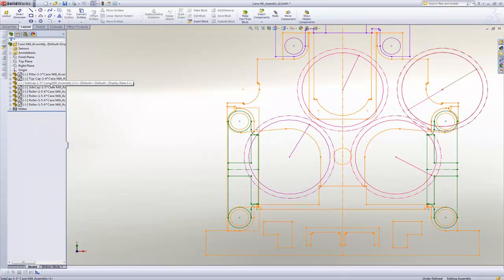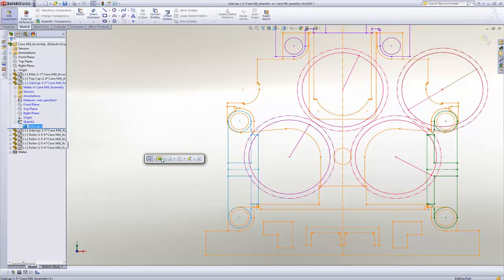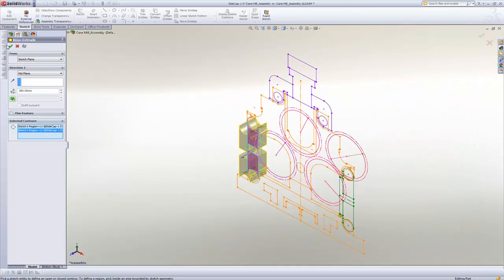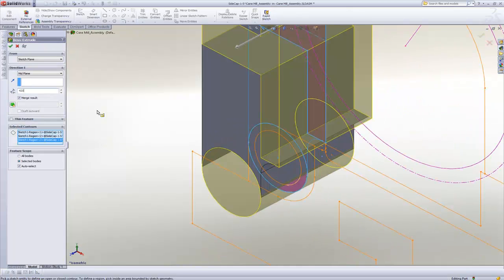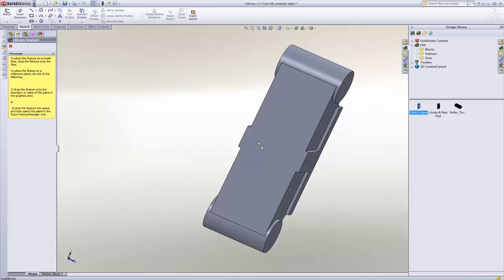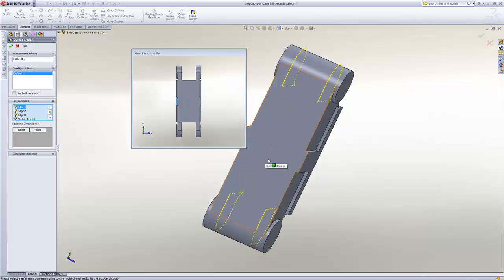Let's go ahead and build side cap part with the help of SolidWorks closed contour selection tools. We will add different thickness to different contours. Now this contour would have a thickness of 380 mm along the mid plane, and the next contour will have a thickness of 420 mm along the mid plane. Standard and regularly used features can be added to our design library so that they can be simply dragged and dropped with necessary inputs.